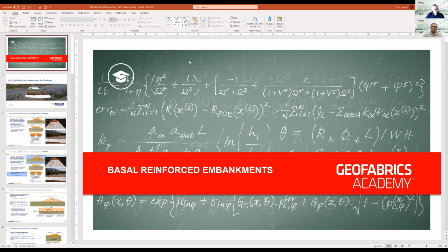So, for example, even if you have a sandy material, which may only have a friction angle of maybe 30 degrees, it can generate its full tensile resistance in probably 1 to 2 metres distance. So, a very short bond length. So the necessity for having highly granular materials in conjunction with the basal reinforcement to develop that bond resistance is really not the case here.